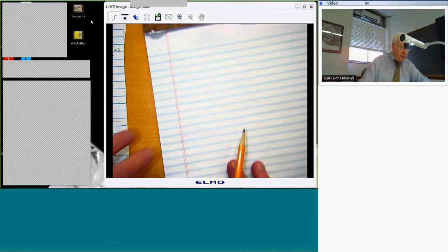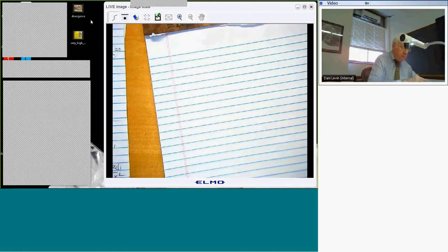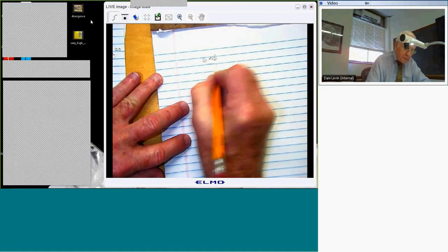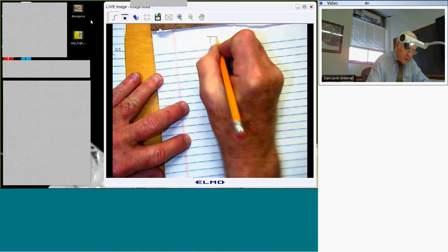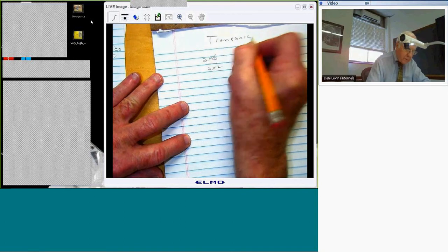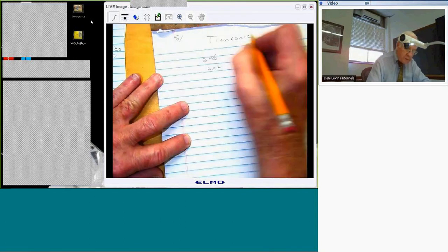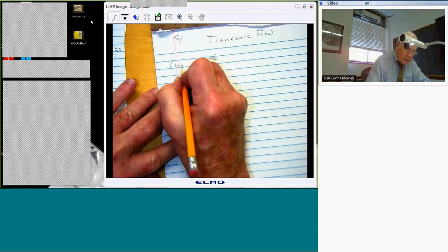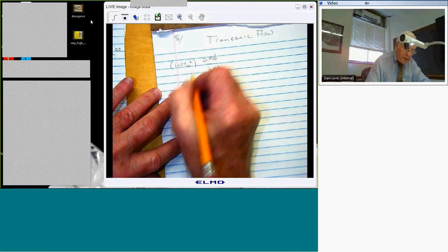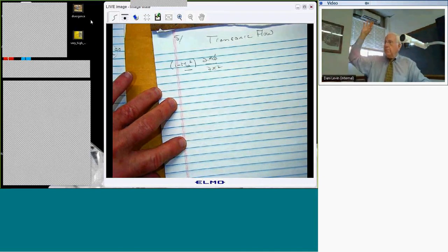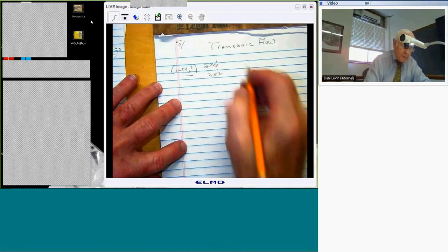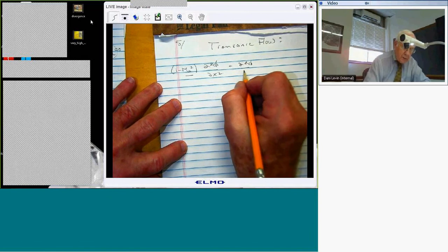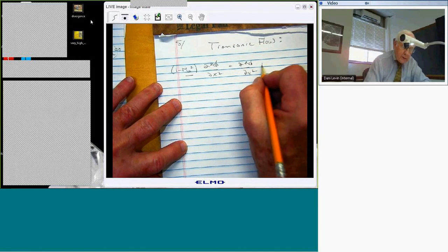Let's just look at this equation again for steady flow. So let's talk about transonic flow for a moment. We have 1 minus Mach number squared. And this is the free stream Mach number, right? This is the mean velocity of flow over the speed of sound. And then we have these other terms. And I'm just going to do steady flow because it turns out, in a way, it's kind of interesting.